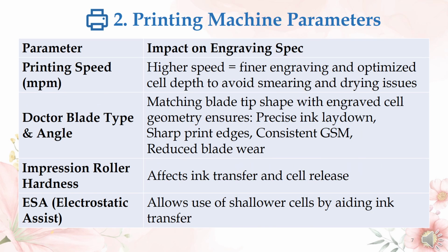Now let's understand printing machine parameters and their impact on engraving specs. Higher machine speed requires finer engraving and optimized cell depth to avoid smearing and drying issues.